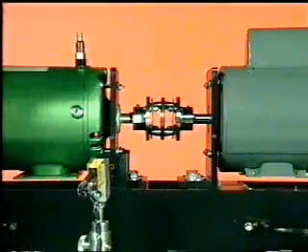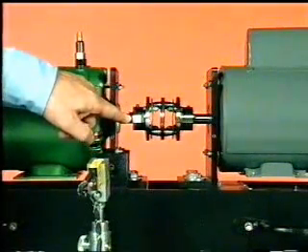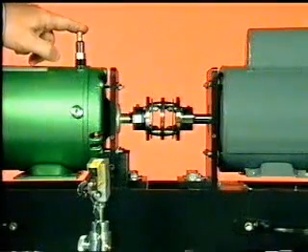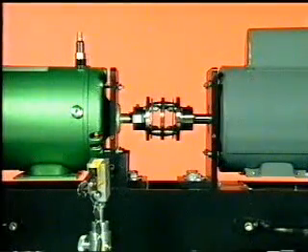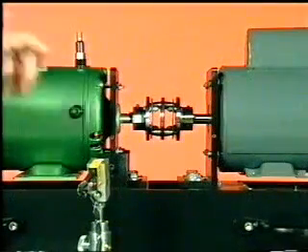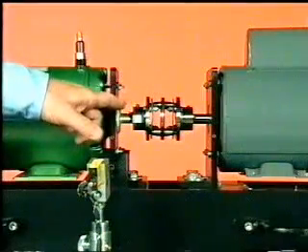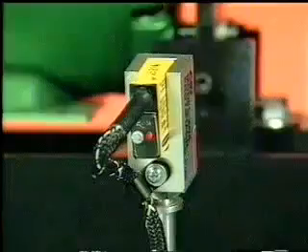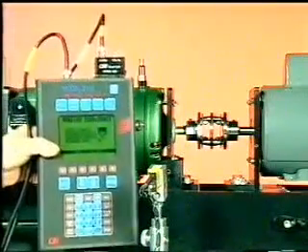On a machine, the phase is normally measured from a fixed or reference position on the rotating shaft to the peak of vibration at the sensor. The reference position can be a keyway or any other location, but is most often simply a position marked with reflective tape. A phototack such as this is then used, which sends a light beam to the rotor. When it strikes the reflective tape, the light is sent back to the phototack, which then sends a signal or pulse out to an analyzer.